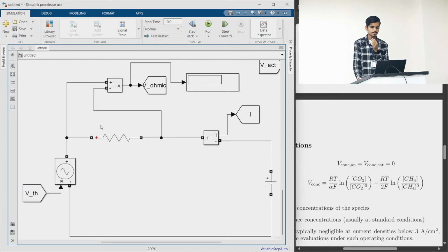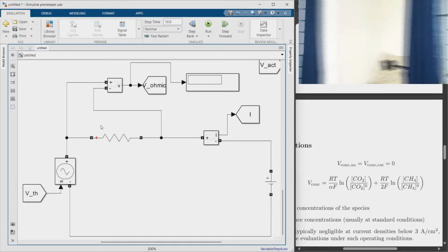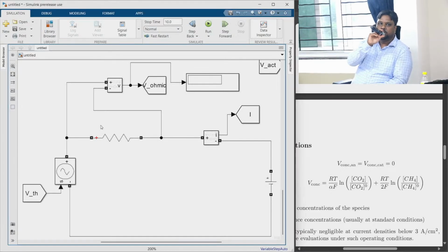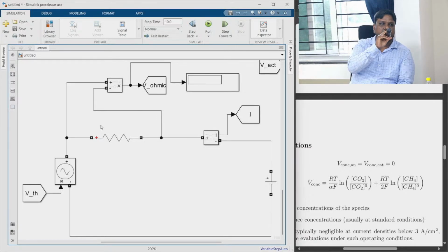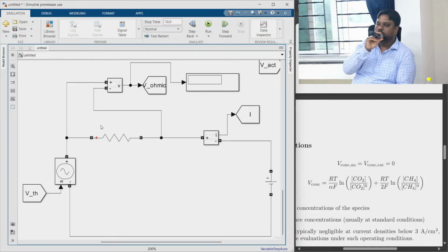So this is basically a dynamic equivalent model of an electrolyzer. But while modeling the potentials, we also included the electrochemical reactions. Of course, we are not putting the chemical equations directly, but we are designing them in terms of an overpotential that is calculated from the measured input current. And in the PDF you were given, all these expressions are shown.